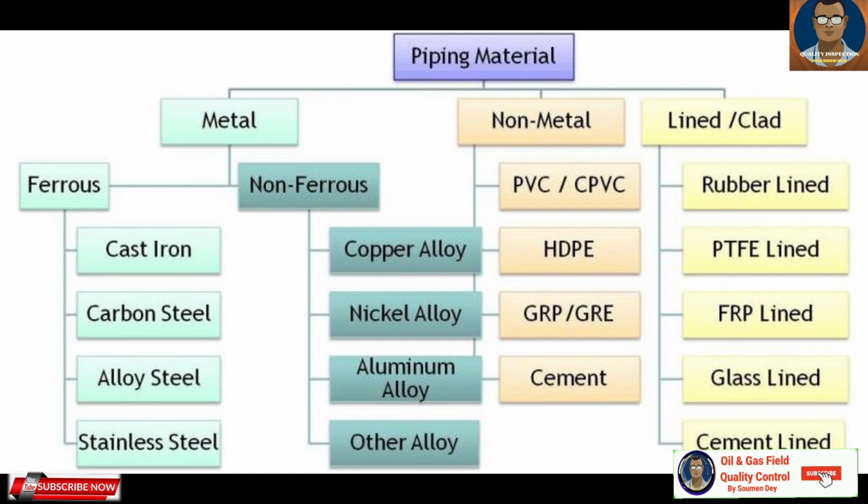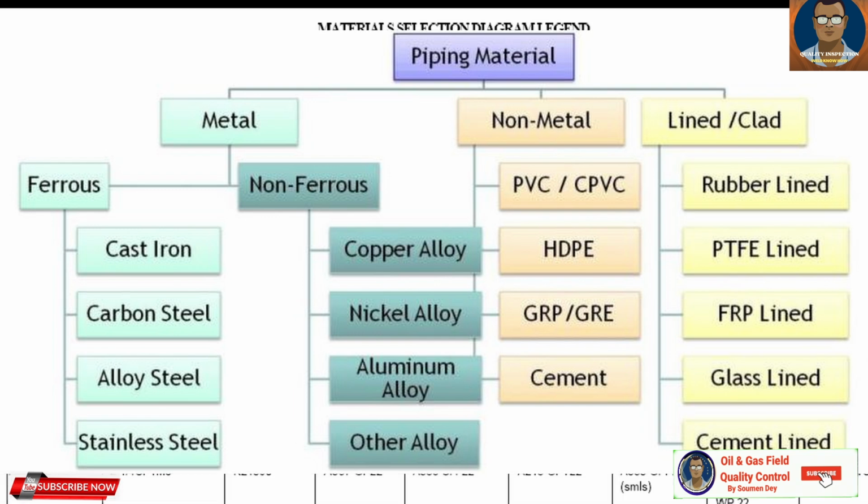Appropriate temperature and pressure margins should be added to the sustained maximum normal operating conditions to determine the design conditions upon which the high temperature mechanical design is based.